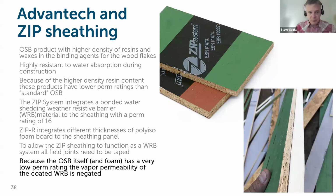Advantech or zip sheathing is an even more resilient and durable version of OSB, with a higher density of resins and waxes in the material. That creates a highly durable sheathing product, especially the Advantech product. You can effectively understand with that product that if it sees any moisture from the inside of the building or from the outside, it will not absorb into the material because of that high density of resins and wax in the product itself.